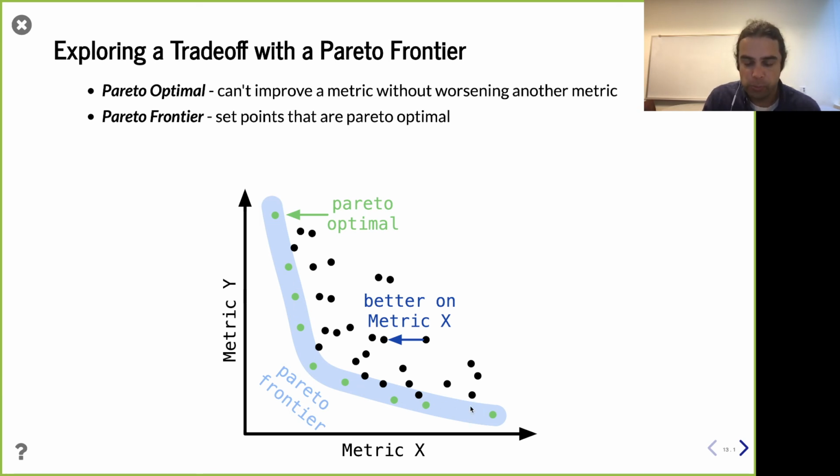And what happens with having Chisel and generators is that it's really easy to push a lot of designs through the tools. So you turn this problem into a compute problem. Just get a big cluster and fire off a lot of design implementations with a lot of tool flows, run the tools many times and see where you are. If you want to identify this frontier, you want to have a lot of points in this graph. You want to be trying a lot of things out. If you can only do a couple of points, you're missing the big picture, and you might never realize these other points exist.